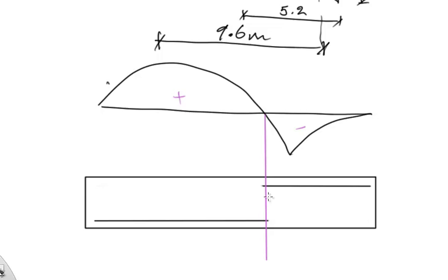whatever on the shear diagram, if you equate the areas before the zero shear point and after the zero shear point, and equate these areas and realize that you need similar areas to come up with the X. That's the short way. The other way is basically finding the equation of the moment diagram, and of course finding the shear and moment diagram equations. Then basically what you need to do is just set the moment equation equal to 0 and solve for X.